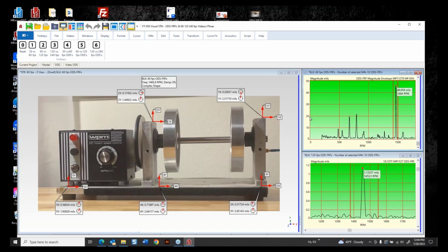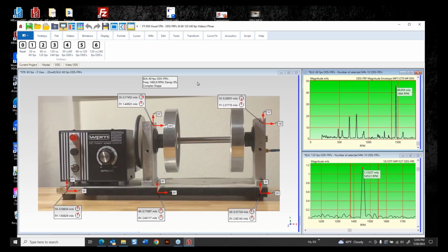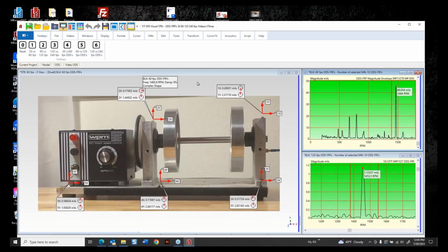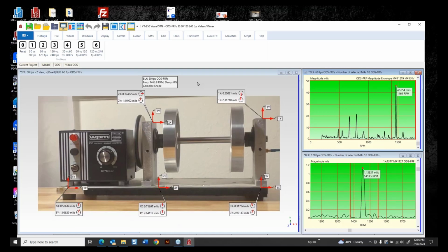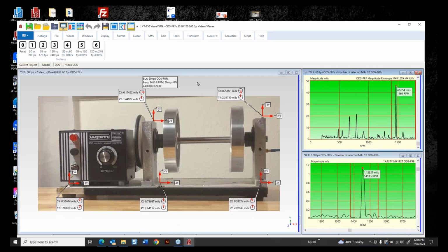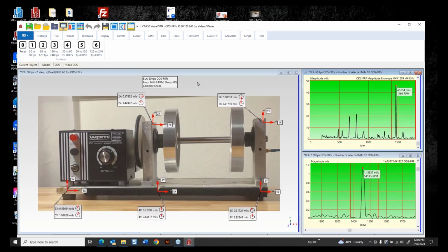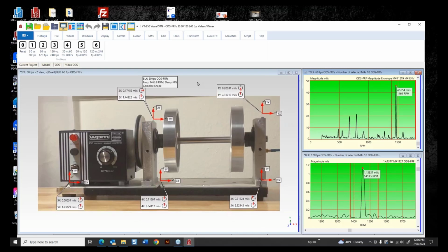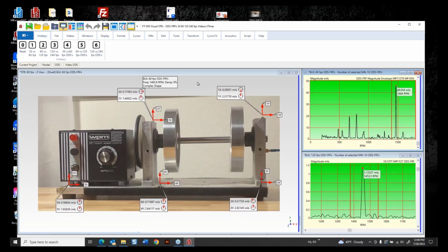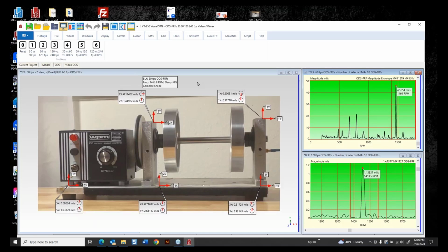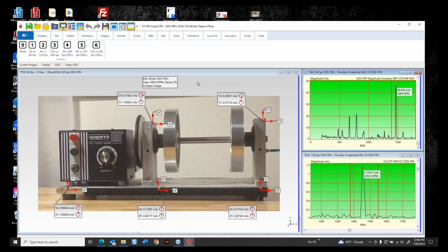We've got customers that are using MEscope on a ship, where the ship is bouncing around in the water and it's very difficult. Now, I didn't show you how to remove all the background motion, but we have commands in MEscope for when the video is moving all over the place because of background vibration. Your hand is going to be very random, so holding it in your hand is probably not a good thing to do, unless you've got a very steady hand.